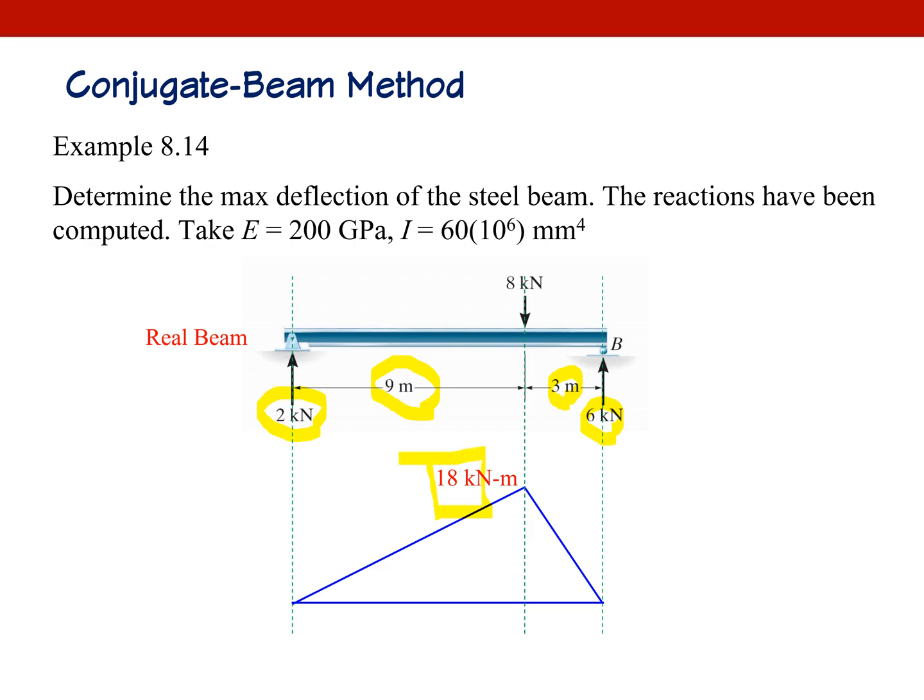And I'm going to have a triangular shape like this. Okay, that is my bending moment diagram, and that is positive. And you will see why I asked you to put a positive or negative sign all the time on your bending moment diagram and the shear force diagram.